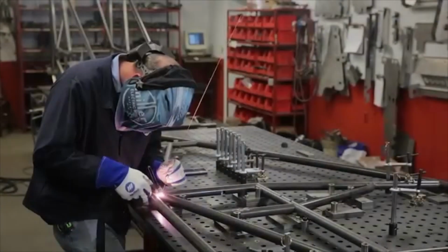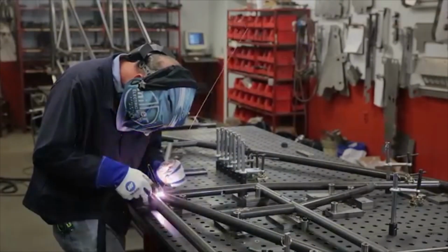We've highlighted the advantages of each welding process. Now we've got to talk about what you're going to do. All of my students that come up to me that are about to buy a welder ask me which one they should get. Well, it really depends on what you're going to be doing most. If you are outdoors working on farm equipment, thick metal, dirtier material, you're typically going to go with a stick welder. If you're working on thin metals, HVAC, or doing frame outs, go with a TIG welding process. If you want a wider range and you're going to be working indoors, MIG welding is probably what you're going to want.